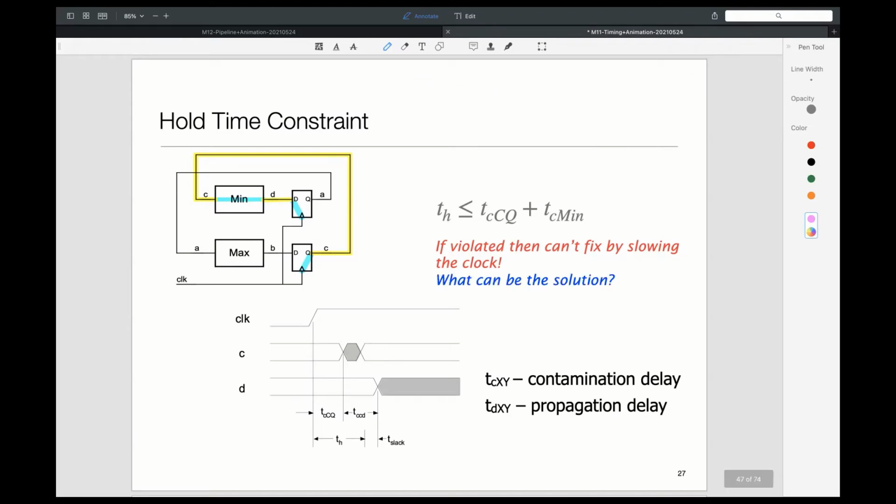So let's say you designed something and you ran your design tool before shipping your design to the fab house, and it comes back and says, hey, there is a hold time violation happening between some pair of flip-flops. This equation is being violated. What would you do? So between some pair of flip-flops, the contamination delays are adding up to less than the hold time. Add gates, yeah. So we have to bump up the right-hand side, right? So we have to add some more.